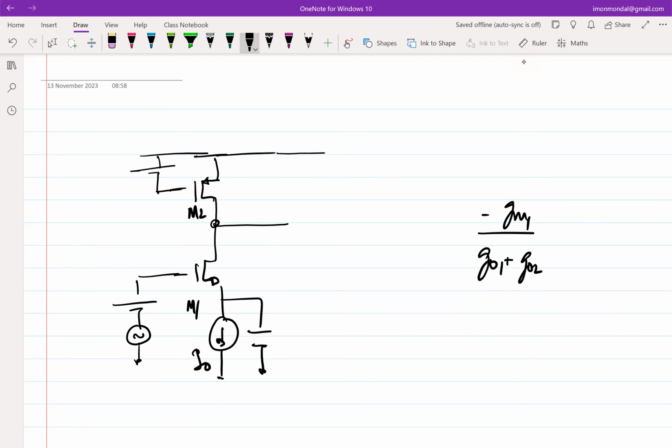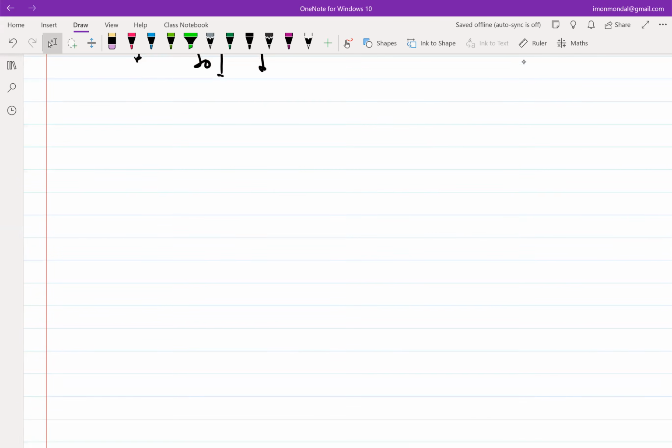So there will be some gain limitation, and the gain limitation will come because of the intrinsic gain of a transistor, right? So it will effectively be GM over GDS. So the question that we are now asking is, if we are limited by the intrinsic gain of the transistor, is there a way of getting rid of that problem? Okay. So now let me simplify the problem down and say, let's take one transistor, and let's say it is biased properly and all.